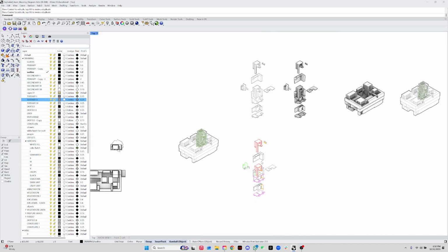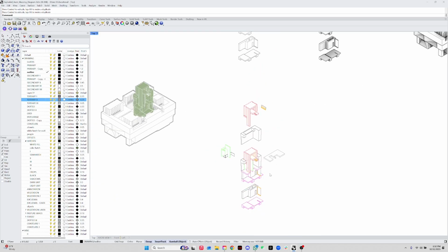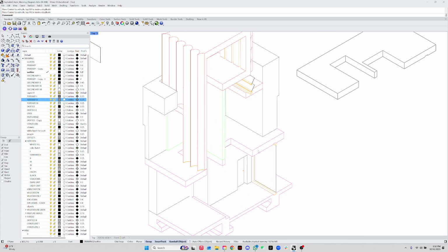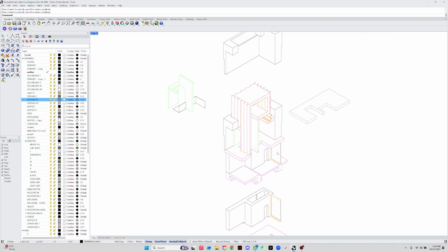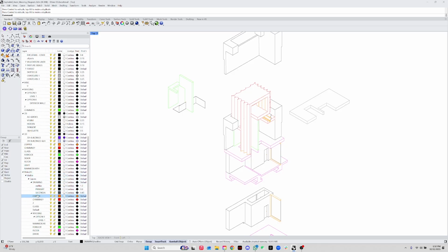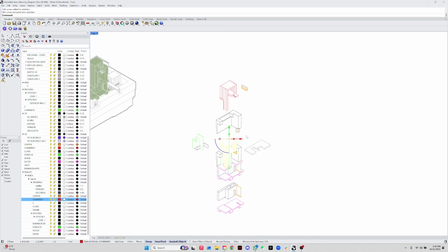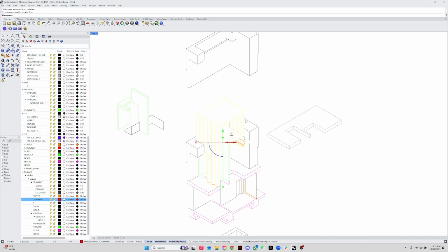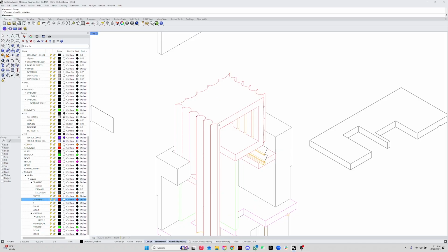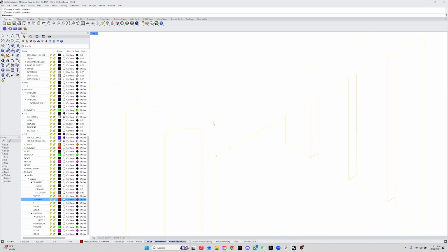Just a couple of pieces of advice when you do this. You see how my model's in layers? Make sure that your stuff is in layers so it's easier to separate. When you have your layers and they don't have any line weights, let's say that you bring it to the drawing template because you have this in a different drawing file. You go to your Make2D layers, and if I have this layer that for me is called chimney, I right click it and do select objects just for this one, because I want to treat this separately than the middle drawing. So I'm going to group this. Then it's easier for me to just pick it and change line width as I wish since it's the same group.